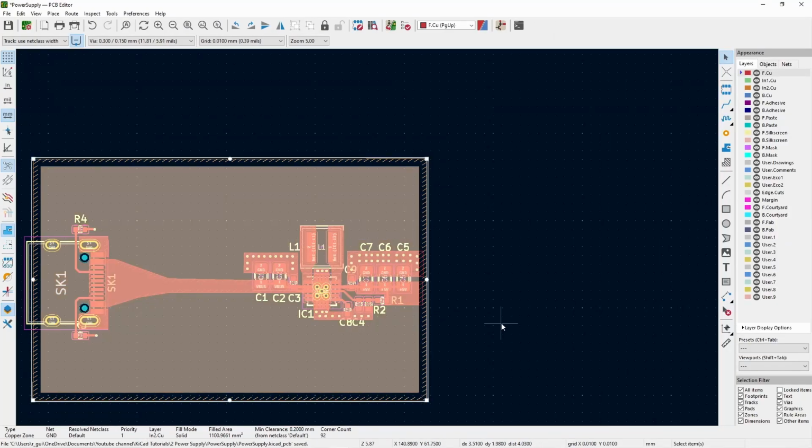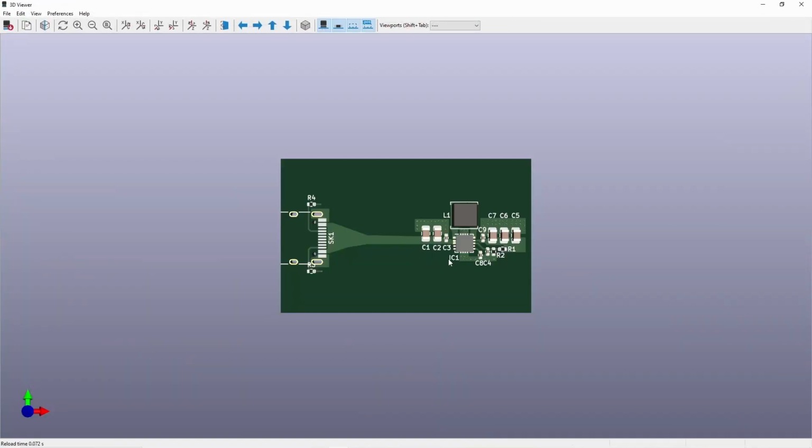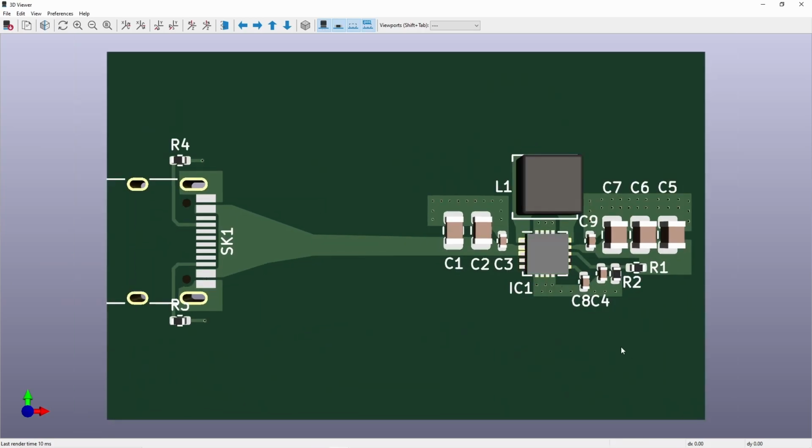And that basically means that our PCB design for now is done. What I will do is add in a boost converter, and to get the 12 volts output that we need, add in the power path controller, so maybe just some switches or maybe a dedicated IC to do that. Add in a location for the batteries, obviously, so there's quite a bit more to do on this, and this board will continue to grow in size as I do that. Obviously, for now, we have the buck boost converter designed and ready to go.